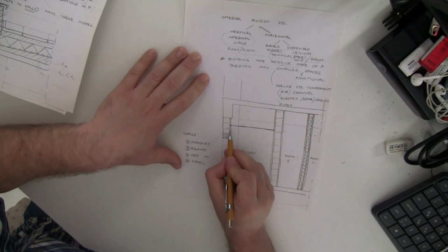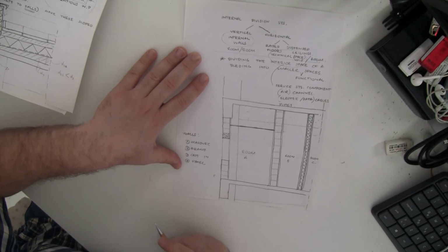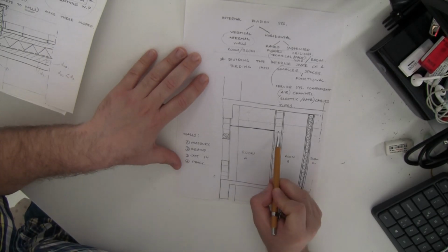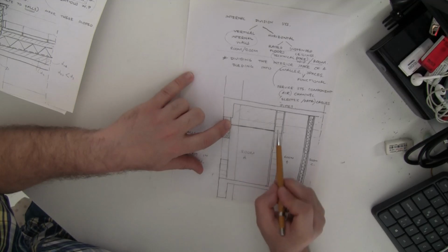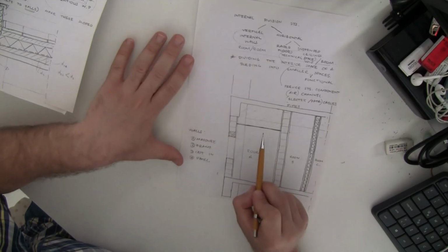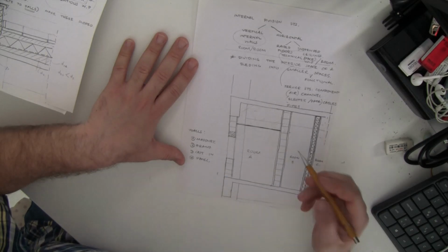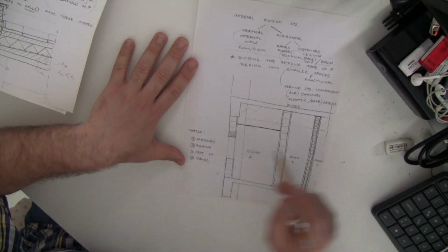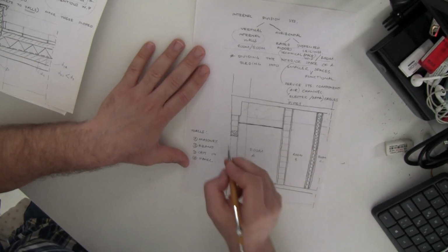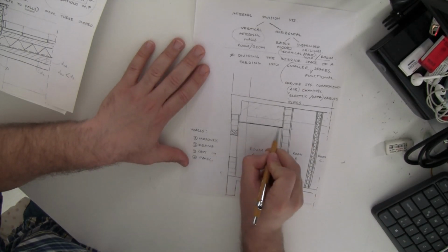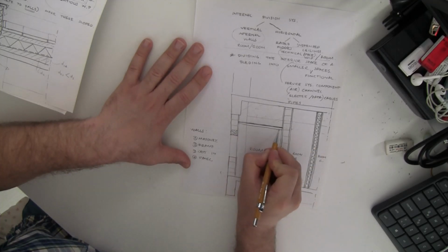And let's assume that we want to place a suspended ceiling there. Don't forget that suspended ceilings usually close this space between two walls. So we do not construct the suspended ceiling firstly and construct the walls secondly. We construct the walls firstly and suspend the ceiling secondly. Okay, what we need to do in order to generate that plane will probably be made of a board.